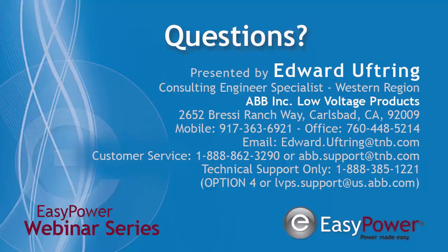Now, as we discussed earlier, you can go through the series procedure and actually run tests to see what the actual maximum is on those two breakers together, but that's time consuming. And you have to go through UL to get the actual listing for that series. We do have a bunch of those lists up on our website. You can see it, but typically when you put any kind of common breakers into a panel, it's the weakest link. The lowest rating is going to be the rating of that panel.